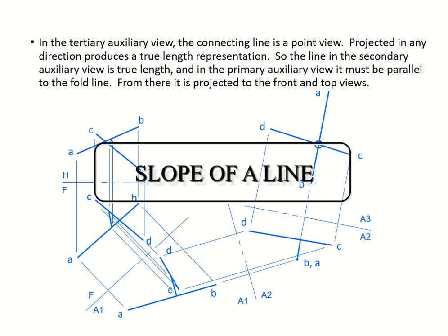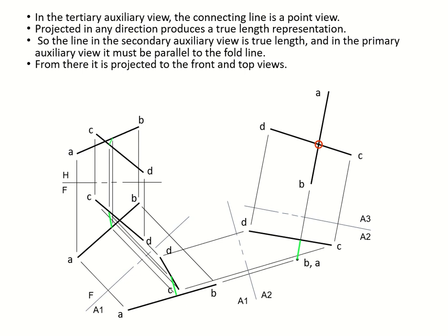Okay, so yeah, that's it for this section. Your true length is right here, AB TL. Okay, parallel is right here. You can see it very clearly. The shortest distance is here because it's point to point. The rest of them has some particular distance from each other. Okay, all right.